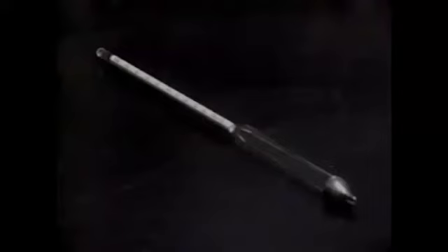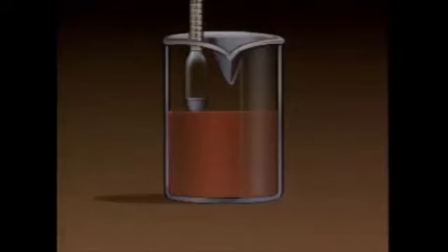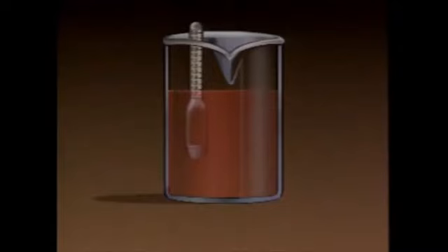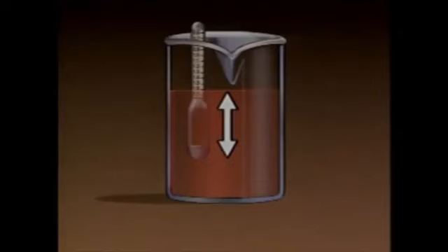One way to take these measurements is to use a hydrometer. Hydrometers vary in design, but this one is basically a sealed glass tube with a weight at one end and a specific gravity scale enclosed in a stem on the other end. A hydrometer works on the principle that a floating object displaces an amount of liquid that's equal to its own weight. Based on this principle, the depth at which a hydrometer floats in a liquid is an indication of the liquid's specific gravity.